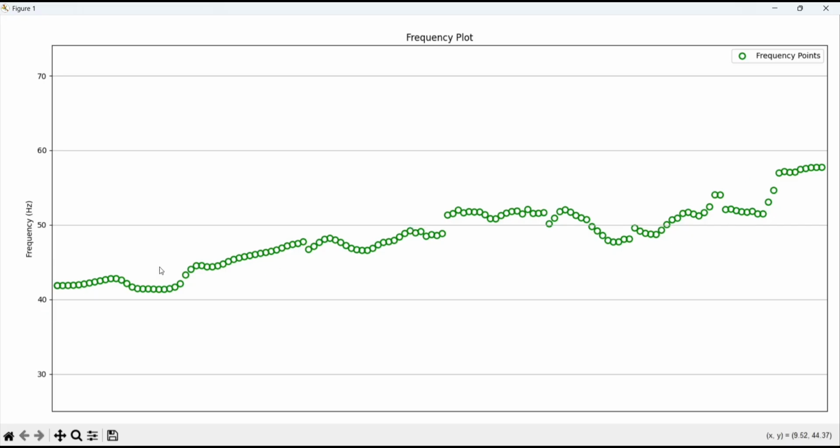So here you can see the frequency varies very much due to this wind speed variation. But if I connect hydro energy or battery energy storage in the main system, then how can this frequency be supported in normal operating conditions also, so that a sustained frequency of near about 50 Hz is available throughout the time.